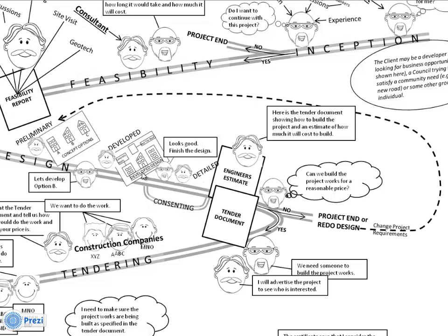So once he's got the developed design, he can submit a consent application, and he presents it to the client. The client says, yep, that's what I like, and then there's a lot more work for the consultant to finalize everything. He does a detailed design on the beams and the columns, windows, everything. So he's designing it properly. He's producing a full set of construction drawings.